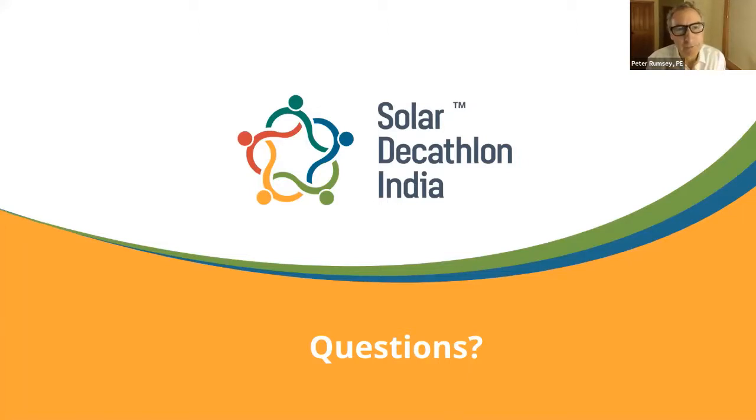Now, there are some differences with radiant. One is that we don't have the fan energy. Fans make heat. All the fan energy in watts turns into heat. That is another load, and this is one of the reasons why I like the radiant system. I very much like radiant. We've done lots of radiant systems in India. We don't have the fan energy, which is lower energy, and we don't have the fan heat, so we have less cooling load.